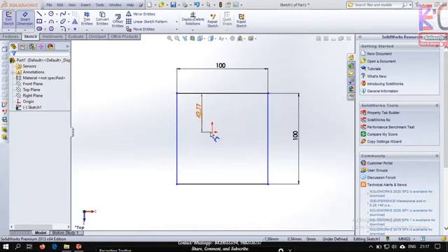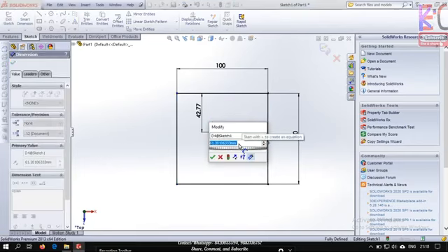Now you want to bring this to the center. How can you bring this to the center? Okay, let me go back and let me give a dimension over here. It's given 61.20. This is in mm. So as we know, from this to this is 100. That means to make it half, it will be 50.